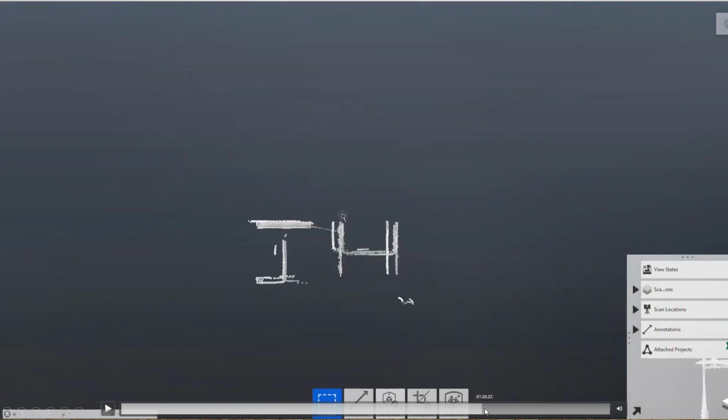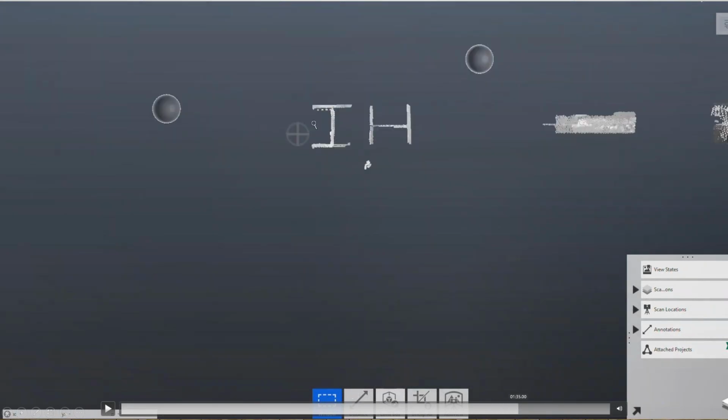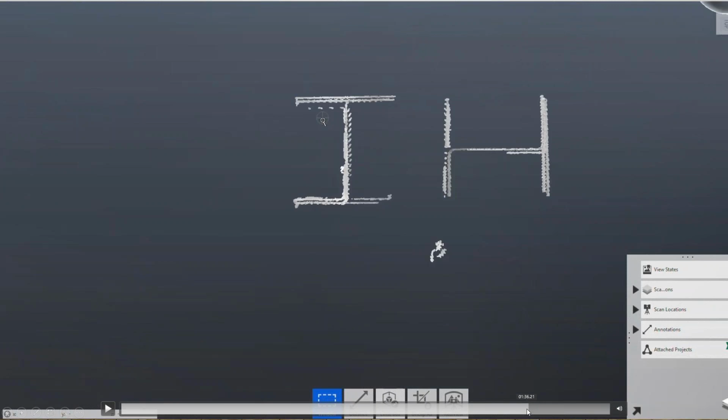Now, what we're going to see here is, okay, so I'm zooming in to one of these I-beams, two of the I-beams. So I've zoomed way in. And one of the cool things about doing a laser scan is you can actually make measurements that are not possible in the field. So here's one of those type of measurements right here, where you can measure the flange thickness using the laser scan. So, the web thickness. The flange thickness you can always measure, but you can also measure the web thickness if you get a scan from both sides.